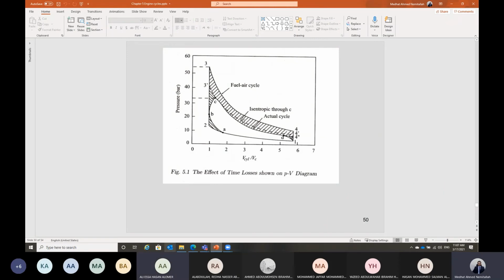This is actually something very important to the analysis for the fuel air cycle. As you can see here, this is the cycle that I have drawn. Also, Shabab, the expansion here is not isentropic. So the specific heat ratio is not constant. If it is isentropic, we have to follow this dotted line. But it is not isentropic, so also we should have some losses. The difference between the dotted line for the expansion and this bold line is due to the difference in the specific heat.